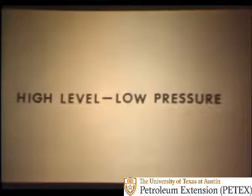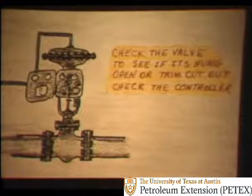One of the more common problems of a combination type is that of a high level associated with a low pressure. This is generally caused by the pressure being so low that it will not push the liquids to the next vessel. Check the back pressure valve to see if it might be hung open or the trim cut out, and the controller to see if it's functioning properly.